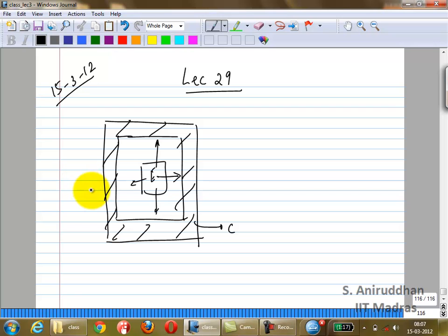Now the other thing you can do, which we'll see a little later, is you can separate out this guy only and make the rest of it another collector. So what will you get? On one side you will get 1/4 the current, the other side you will get 3/4 the current. You can have a multi-collector transistor, single emitter, multi-collector. So you can bias two different circuits, for example, using just proportional currents.